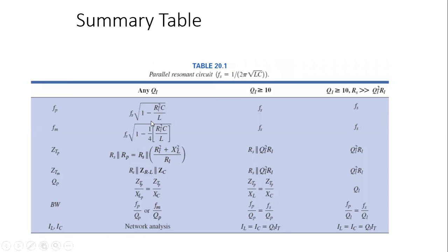Frequency is changing in the parallel resonance just because the circuitry is dividing. Every time, because of the connection of the RL, one time combined, one time separate, that's why the resonance frequency changes every time. So in the second case also, you can easily find the impedances, how my RS is in parallel toward the RP, and this RS will be connected. So in this way you need to take care of the quality factor along with your reactances.